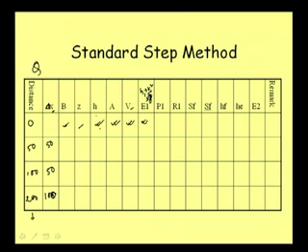Then from all these values we can calculate the perimeter at this point, and the hydraulic radius at that point, because area and perimeter are known. Then we can calculate SF, the friction slope, as I have shown already, by using Manning's formula. But what will be the SF bar, that we cannot calculate at this point.